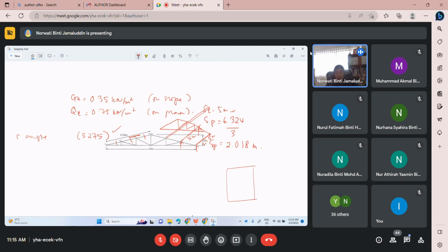length, I don't think you need 5 meters only. Building length could be up to, let's say, 15 meters. So your purlin will run until 15 meters. Then you know that after 12 meters, because that is the maximum length of steel, you need to do a connection.